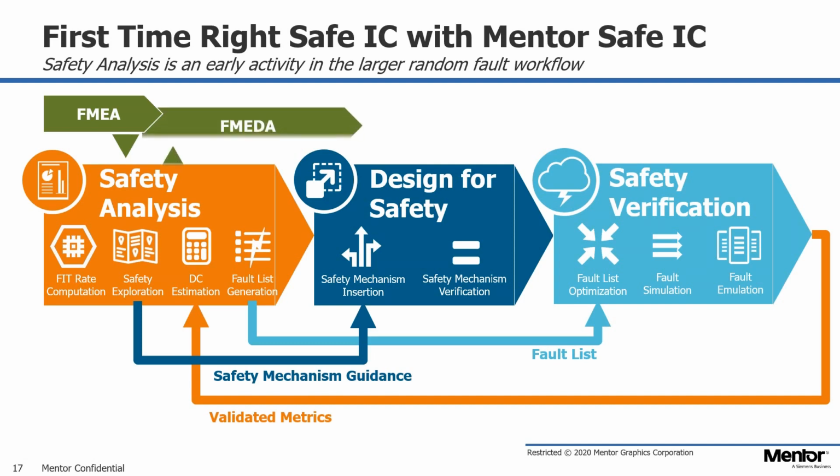And when this loop is closed, then you can provide the metrics for diagnostic coverage, latent point failures, single point failures, and basic overall fit rate into your FMEDA to close the loop and to provide the necessary values to conclude the analysis step. This is what we as from Mentor call Mentor Safe IC, because this is the complete flow which we can provide with our tool suite.